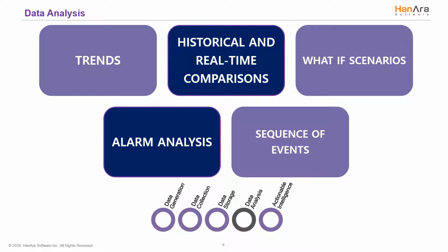Data without context is not helpful and can even be misleading. Knowing that the temperature is 540 degrees provides me with nothing. Knowing that the boiler was 575 degrees at 5:05 p.m. today and has been steadily increasing since yesterday, while pressure remains constant, is meaningful. With the context, data becomes meaningful.